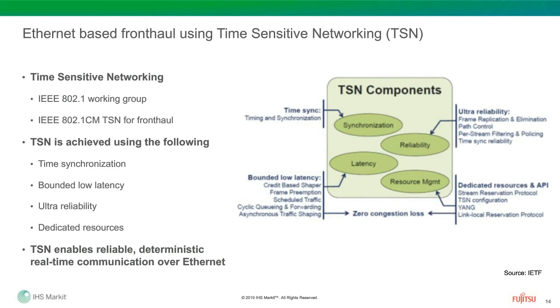Bounded low latency will guarantee a not-to-exceed end-to-end latency required for critical applications. The use of frame preemption for long blocks of Ethernet traffic will maintain low latency variation, or jitter, for critical 4G and 5G traffic. Frame replication and elimination over disjointed paths avoids frame loss due to equipment failure. Using these components will guarantee data transport with bounded low latency variation, and extremely low loss.